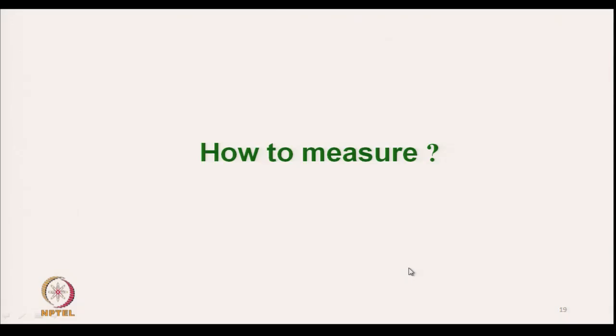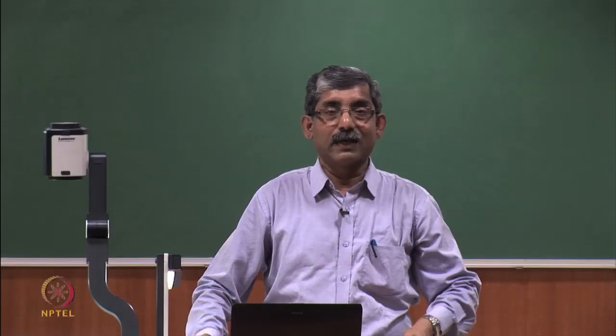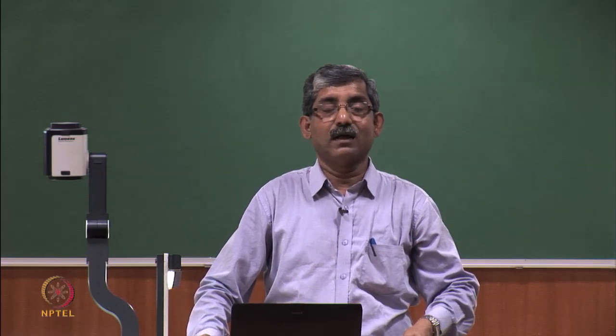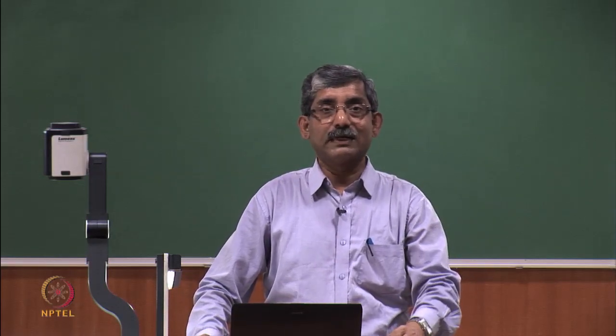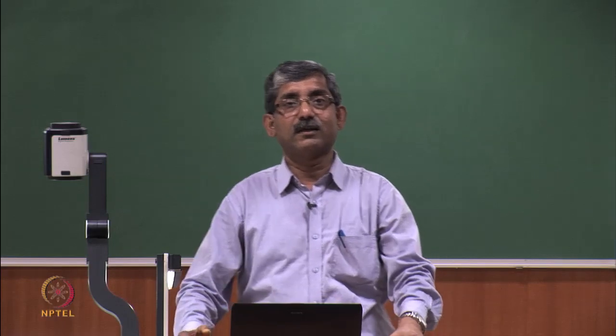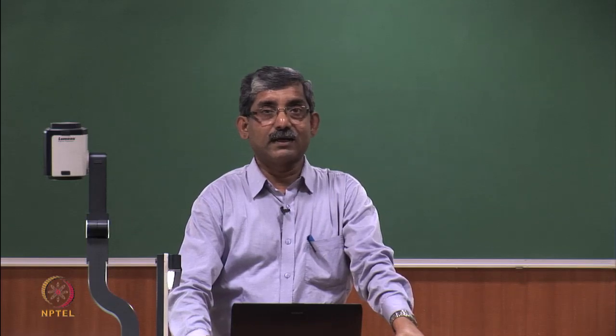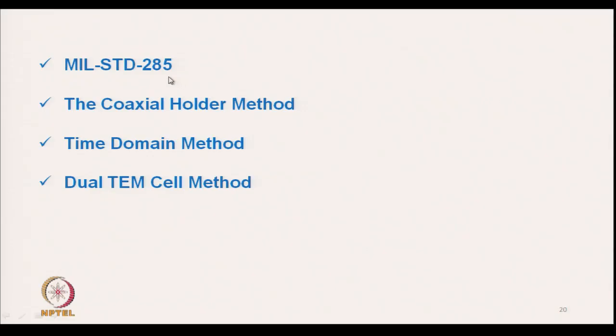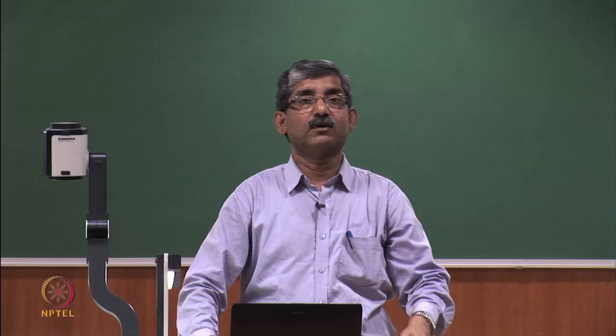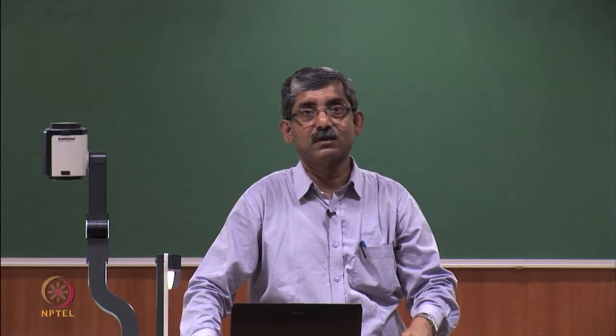So, how to measure? We have understood the shielding mechanism, and now we will discuss the measurement techniques. There are different techniques available: MIL standard 285, which is a military standard. We can use the coaxial holder method, time domain method, dual TEM cell method. So, these methods are very commonly used.